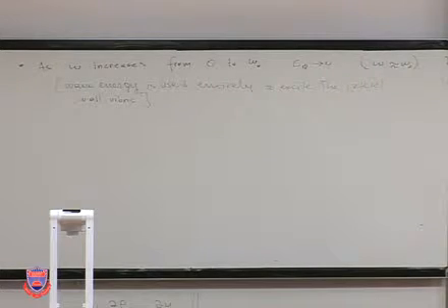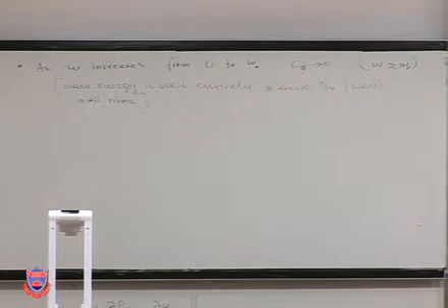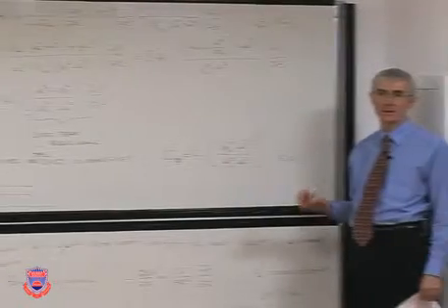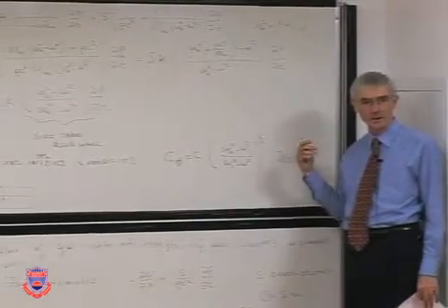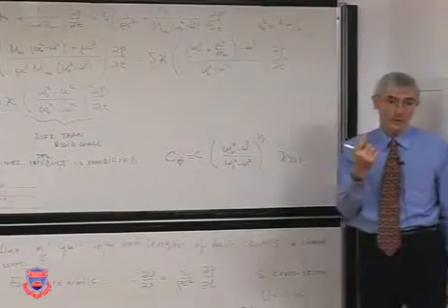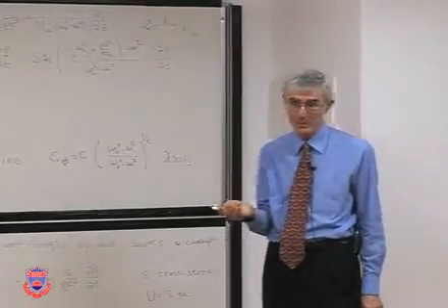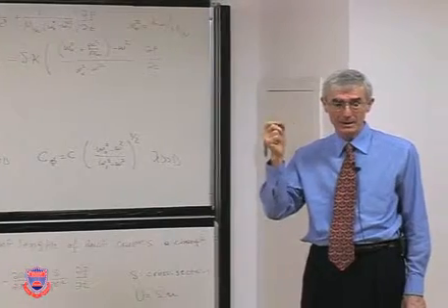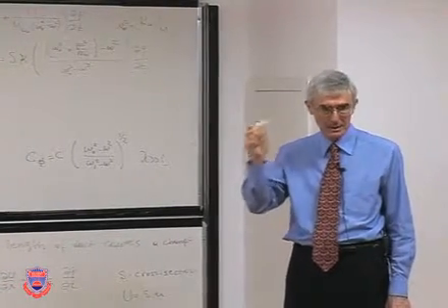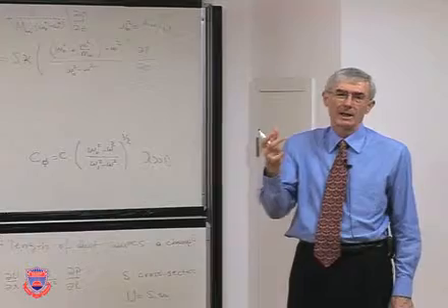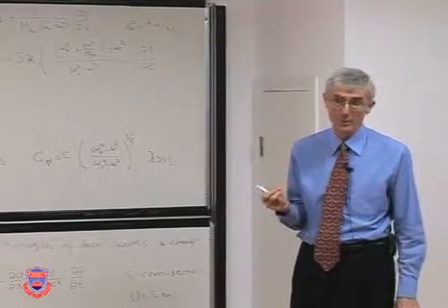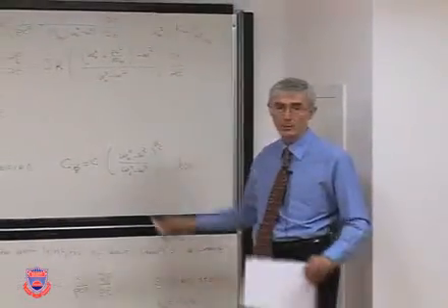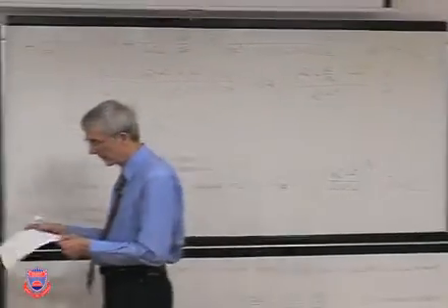Now suddenly you see that you have a flexible pipe. You adjust its flexibility so that it just prevents sound from transferring, but at only one frequency, not at all frequencies. So if you have, let's say, a pump that's sending pulsations at a primary frequency with a lot of other frequencies, you can get rid of the primary frequency if you are able to adjust the wall flexibilities. Okay.